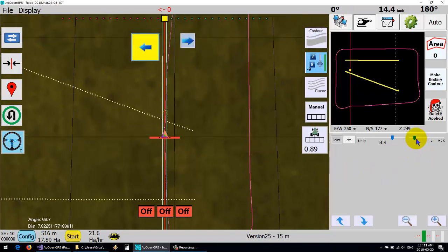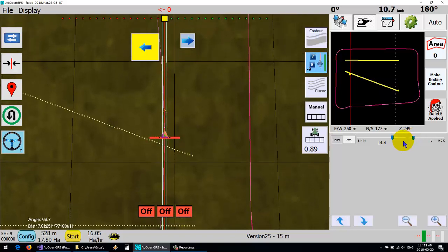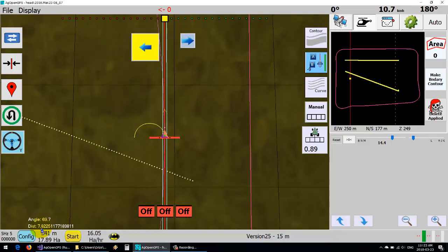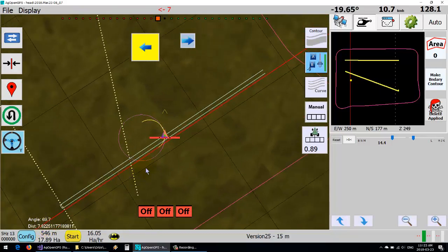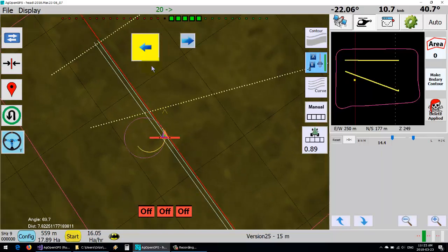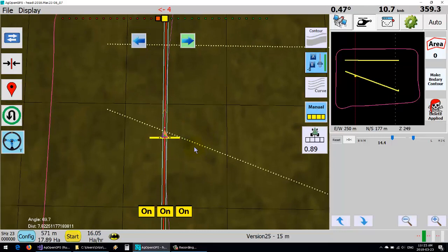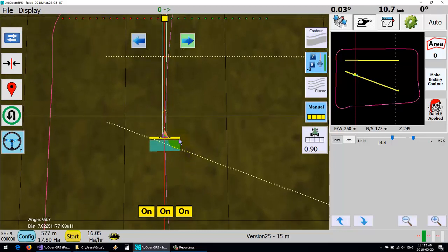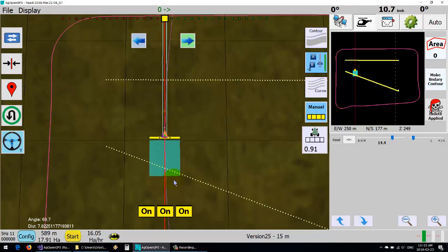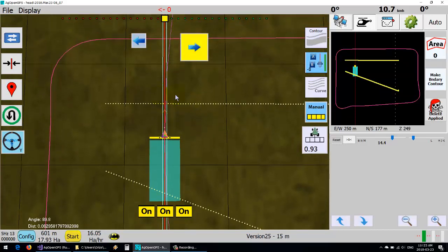I want to go that way. So here you can see the angle is 69.7 and an additional 7.8 meters it needs to travel because that's on an angle. It doesn't matter which angle you come from, that sort of thing. Now it should turn on. See, now that corner turns on right at the headland. Before, if you set it there, then it would go past this headland.